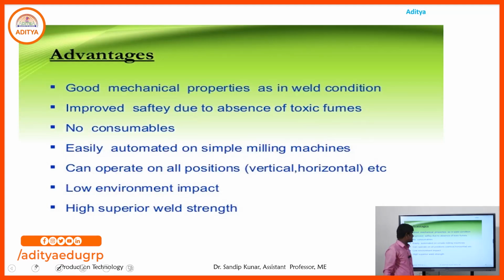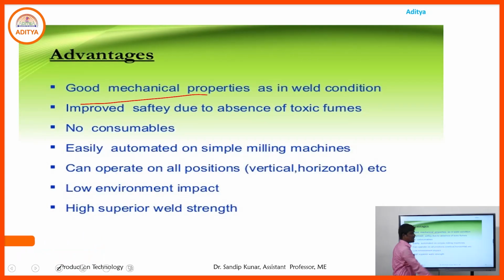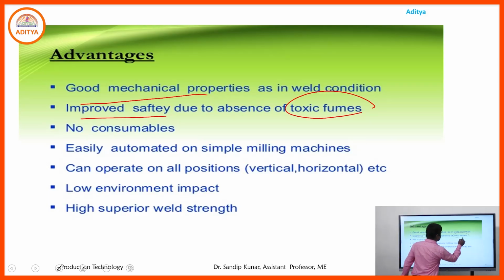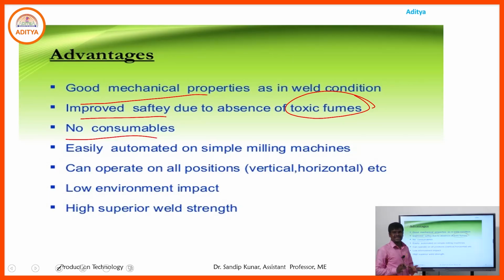What are the advantages? We get very good mechanical properties in this welding process. We also improve safety due to the absence of toxic fumes, meaning no toxic fumes are generated, so it maintains safety precautions. Another advantage is no consumable, meaning no extra consumable electrode or filler rod is used.